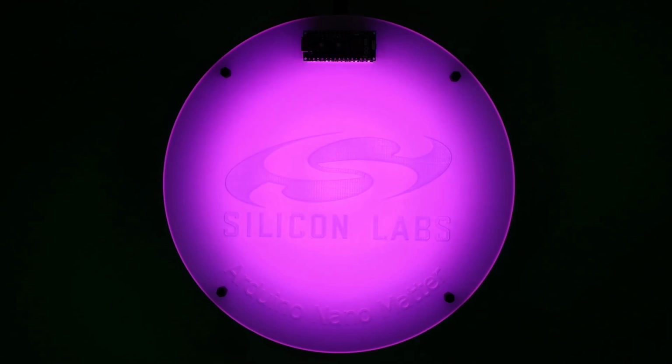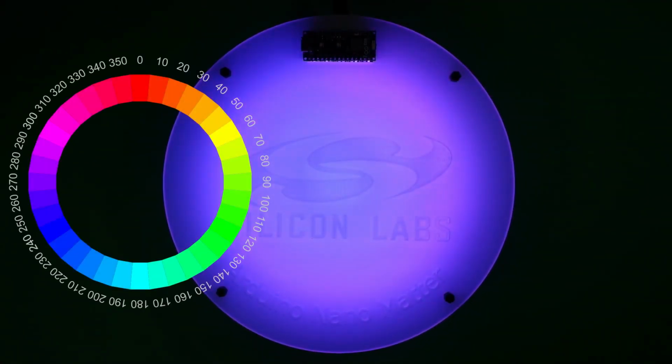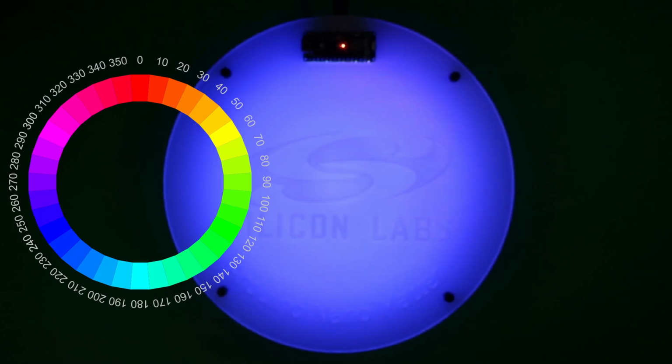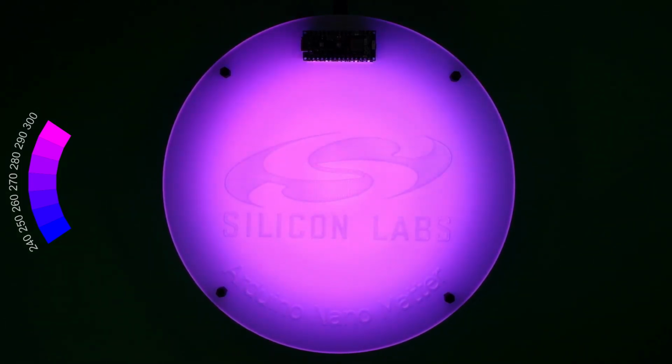In the second step, we will keep the solid modes in place, but add 2 new modes that will display an animated gradient between the two endpoint colours. Pressing the button again will go to the first of these. Here we have a gradient that goes between the two colours, following the short path around the colour wheel. As the colours I selected are only 60 degrees apart, this is quite a subtle effect. The gradient is animated until all the LEDs are set to one of the endpoint colours and then reverses.